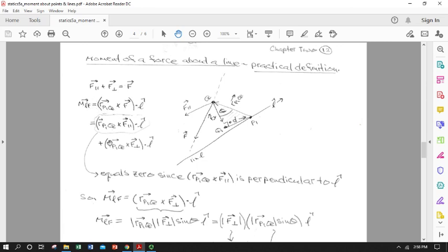So I can use these definitions to pick those different parts. And we've got, again, our line of force here. Q is a point on the line of force. And here's my shaft, line L. I got a point P1 on it. I can define perpendicular portions of this with my angle theta. So here I've got a point Q1 and a distance that is perpendicular. So I can take that perpendicular portion now, F perpendicular. The remaining is the parallel portion.